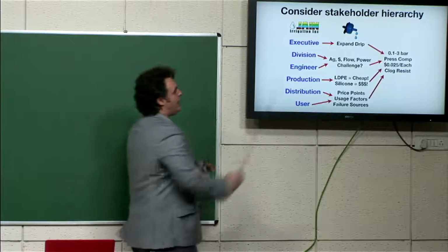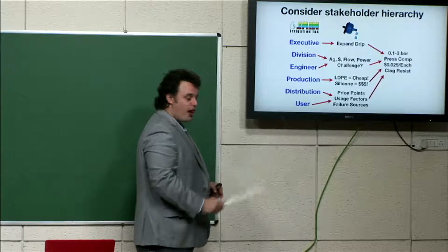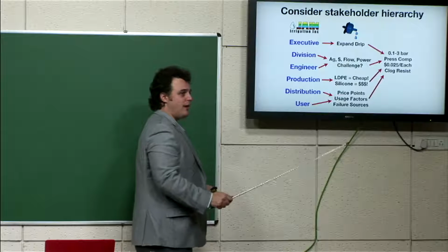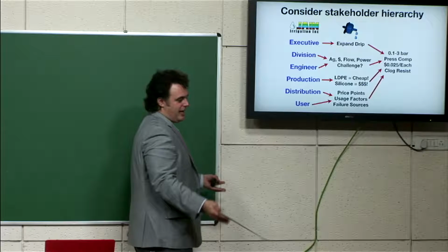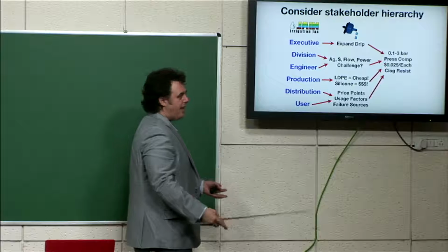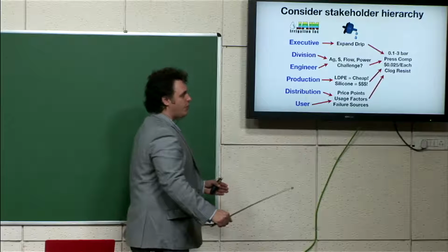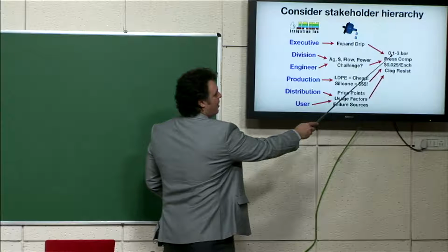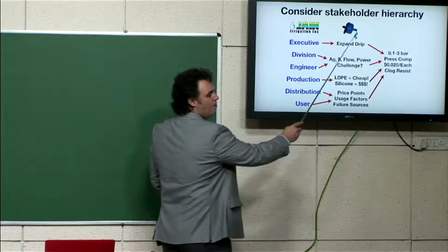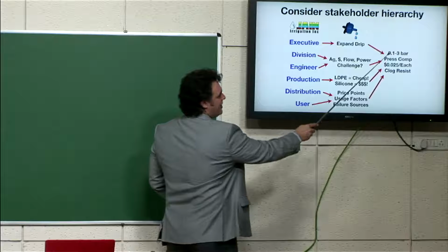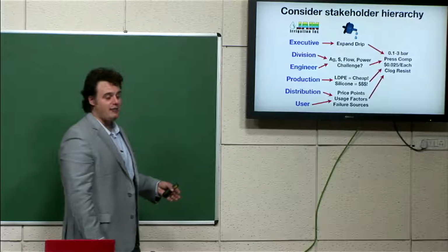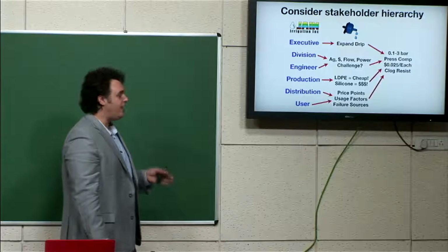What drives that power is the pressure required to move water through the system, right? Power is pressure times flow rate. Flow rate, the plants need a certain amount of water per day, so pressure is what we could reduce. And so that made us realize that if we could go from, typically these run at about 1 bar or 1 atmosphere of pressure, if we could cut that by about 10 times, we could cut the capital cost of the system in about half. Massive, massive sensitivity to overall costs.